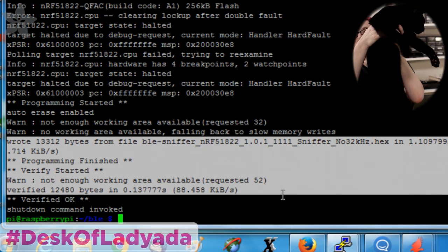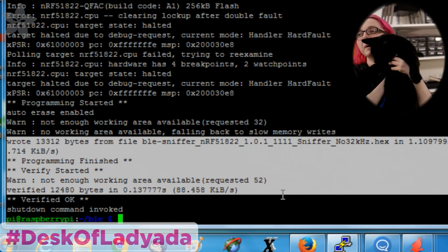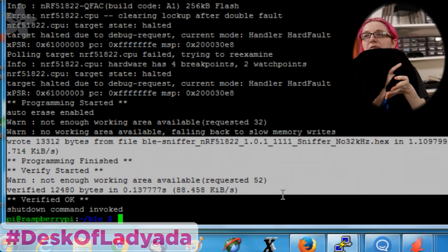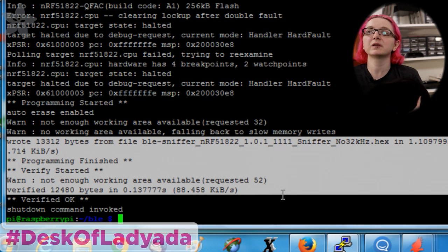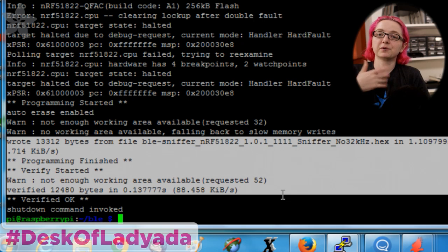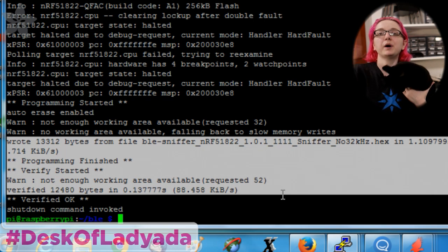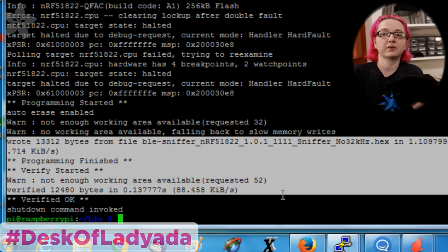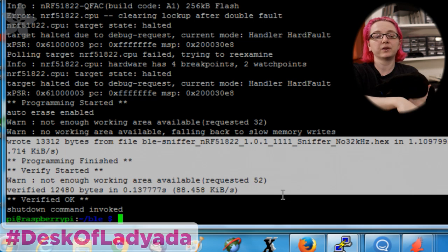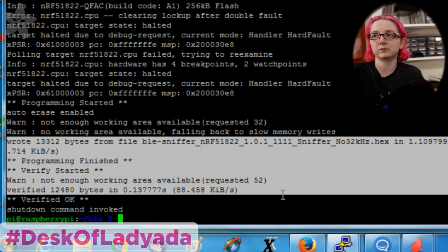You don't have to set up USB connections and timeouts and make sure your buffers are all working. Especially if you are doing this slow memory write for the Nordic chips, you're probably sending 1 byte back and forth per packet. With USB, you're going to slow it down because you have to wait 1 millisecond or whatever for each transaction. With the native pins, it's really fast.